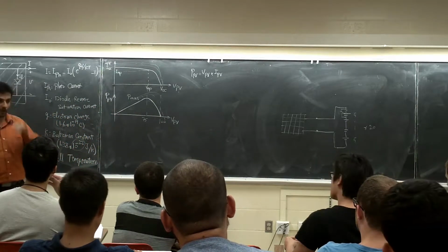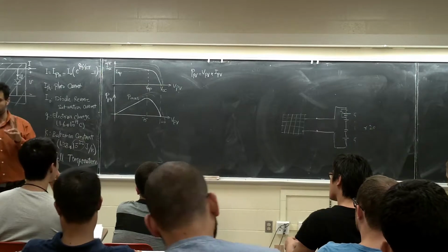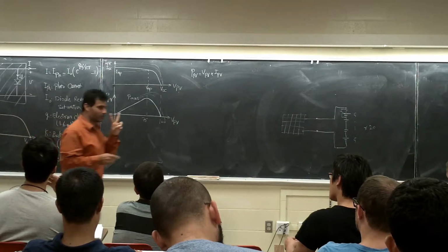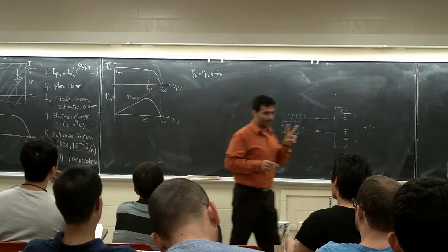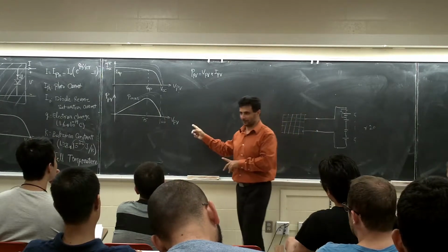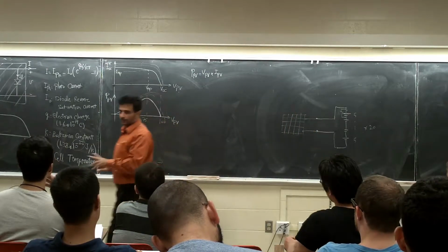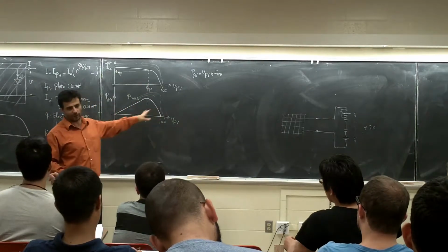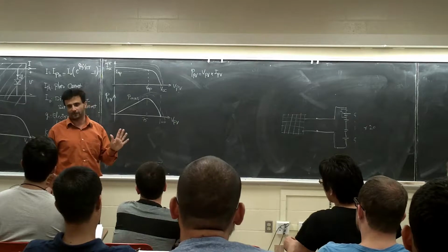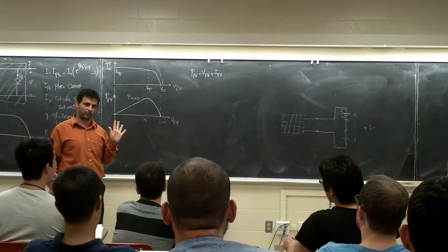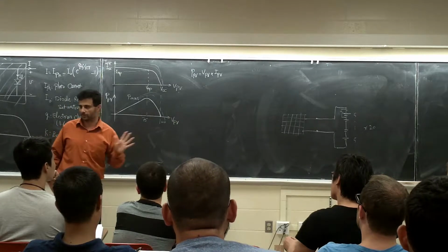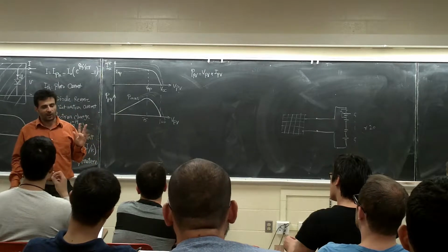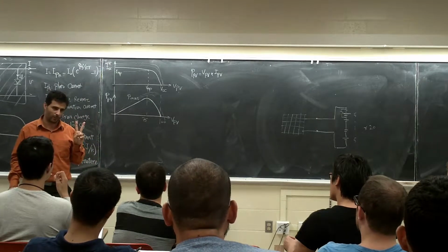They call it maximum power point tracking. There are two different levels of tracking. We call this one electrical maximum power point tracking. What do I mean by electrical? We will change the voltage and those things and we figure out this point, right? What's the other level? It's expensive. Usually they don't do it. In 90% of the places they don't have that one. They call it 2-axis maximum power point tracking.